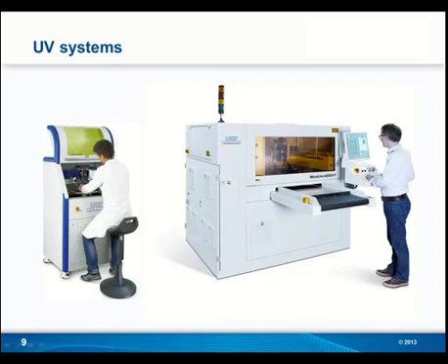I have a question from John, who wants to know about the type of software package we need to control the lasers and if they work off of Gerber files from circuit design. And this is one of the great benefits of UV. Yeah, absolutely. The software that comes with the laser systems is LPKF CircuitCAM and CircuitMaster. And it does import DXF, Gerber, GerberX, HPGL, ODB++, and Excellon files to bring in that data.